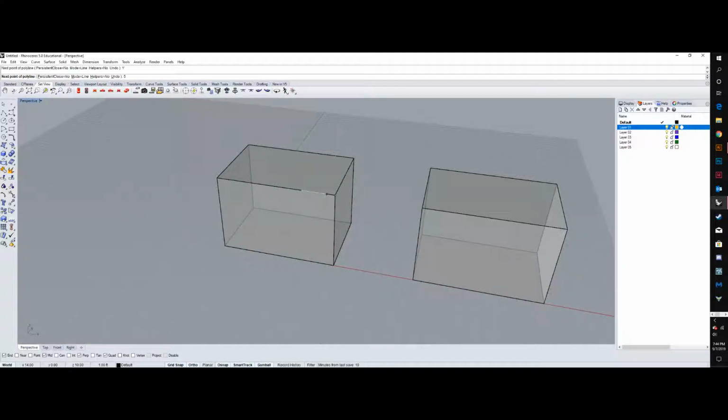Let's do 5 feet in this direction. Notice it says perpendicular. That is a 90-degree endpoint intersecting with that edge. So I'm going to hold it there and type in, let's take out 5 feet. And I'm using that as a reference. That perpendicular is a reference, not an actual place where I would like to put that point.